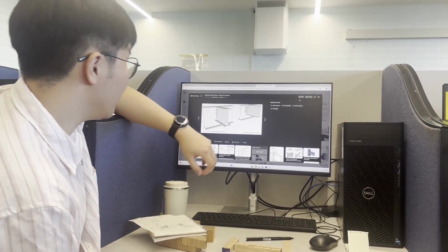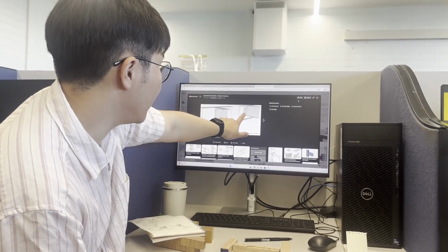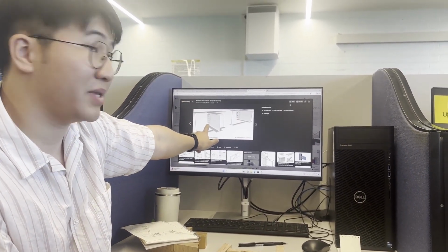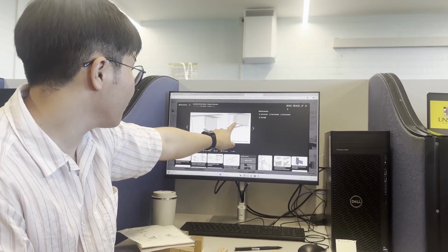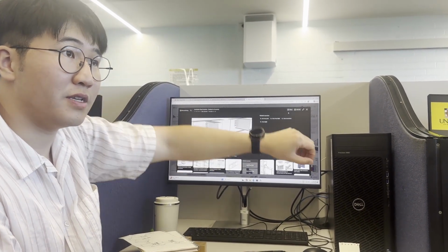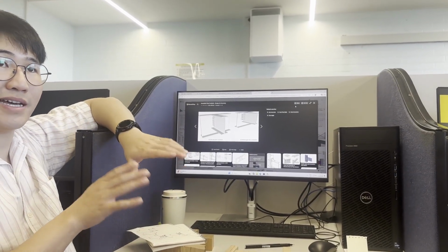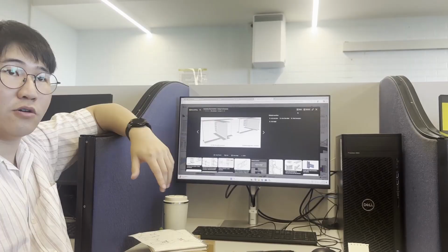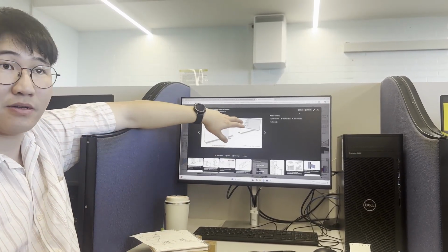Yeah. The other thing that you might see is an equal angle used as a cleat, instead of a plate. Now this is pretty common if it's not shop welded. So if you're in a situation where you need to site weld, say that primary beam already existed, and then you're retroactively adding another beam there, right?